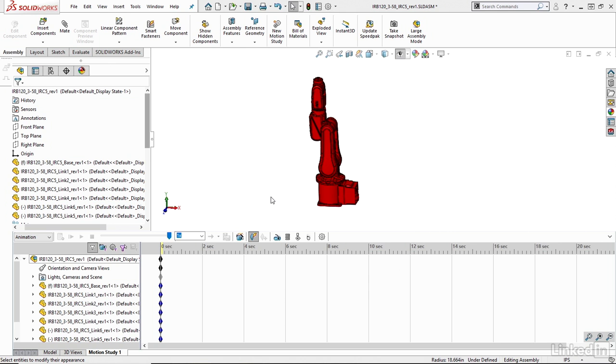And the two types of mates that we'll be using most often with motion controllers are the distance mates and the angle mates, as they can hold exact dimension values for translation or rotation. So a good example of this would be this robotic arm assembly here, as we have a bunch of different links that we might want to control mating angles of.